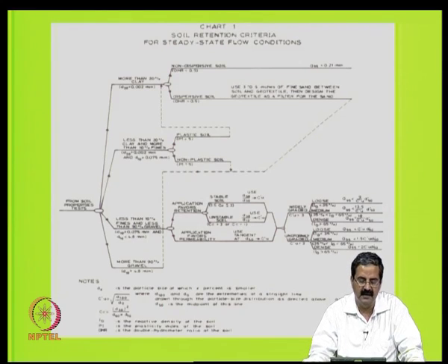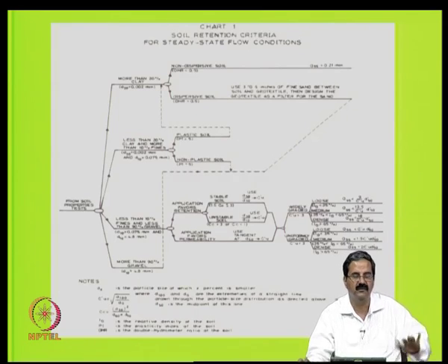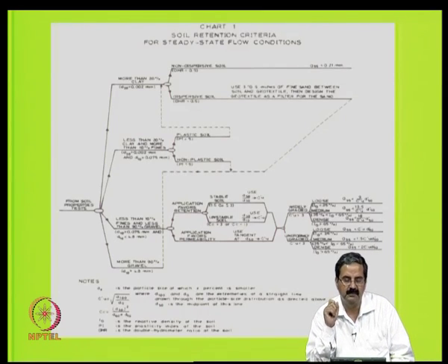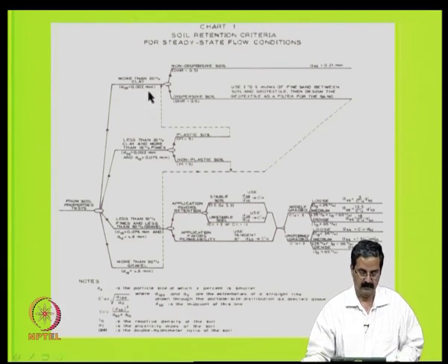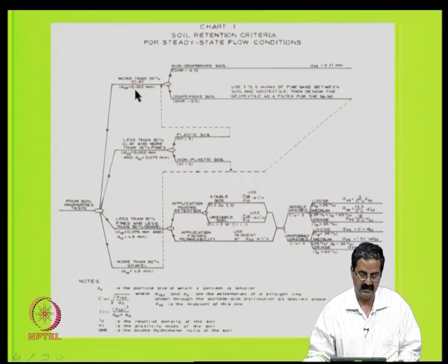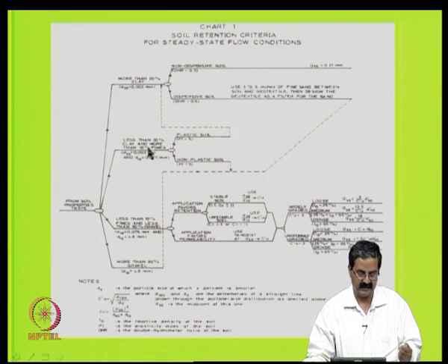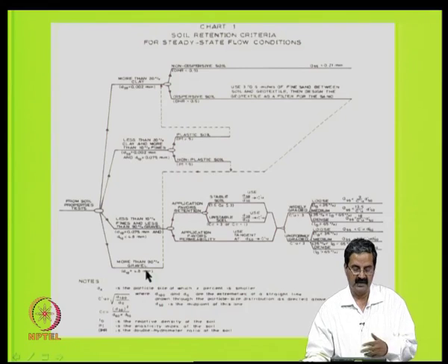What you do is you want to do a filter stone pitching or a filter pitching for it, and you want to come out with a simple design for the filter. That is our objective. So, what is the procedure? You take soil samples from the area, then find out its clay size, the percent clay, more than 20% or less than 20%. What is the clay content? Once you know the clay content, you can use that appropriately.